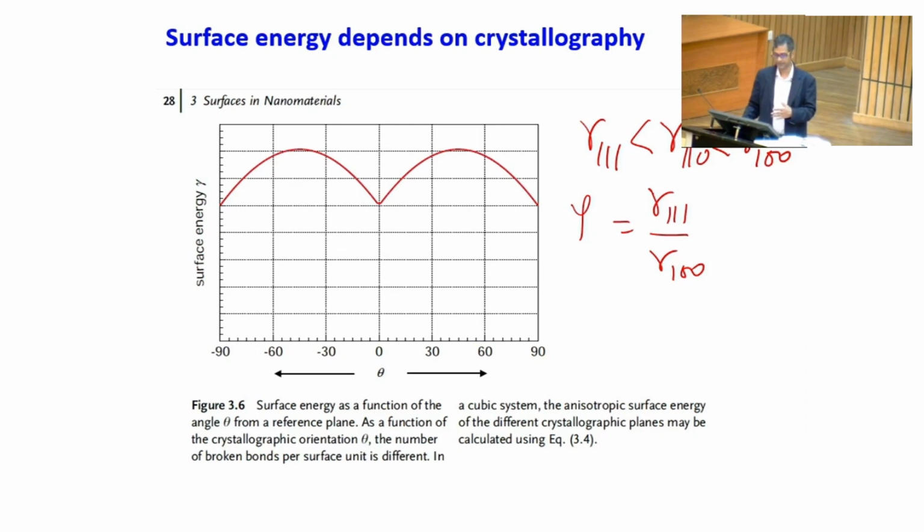Okay? So now one can have cubic anisotropy in the case of cubic crystals, one can have tetragonal anisotropy in tetragonal crystals, one can have orthorhombic, hexagonal. Different kinds of crystals have different kinds of anisotropic parameters. And that is how we can actually get generalized expressions of gamma, which we may discuss sometime later, not now.